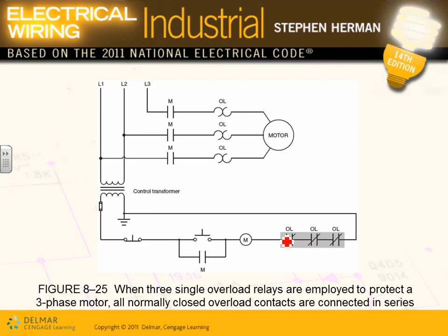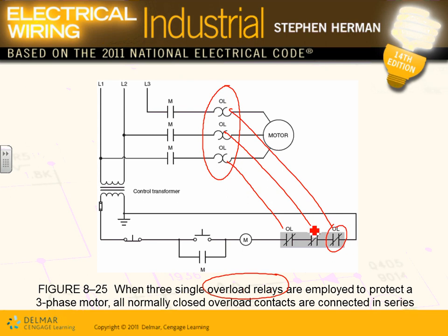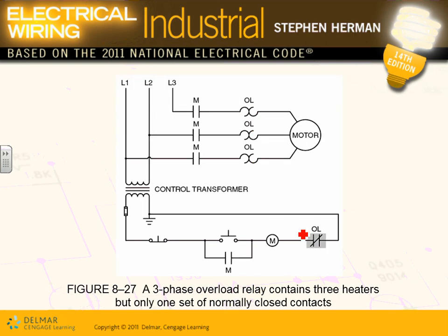Here's what we're talking about, guys. Look at this. I have my overload relay, an electronic relay. Can you guys see there's 3 of them sensing, and each one of them is driving a contact? These are driven by these 3 overloads. This is your electronic. If you have a heater, can you guys see these 3? All of these 3 are driving the same contact to open.